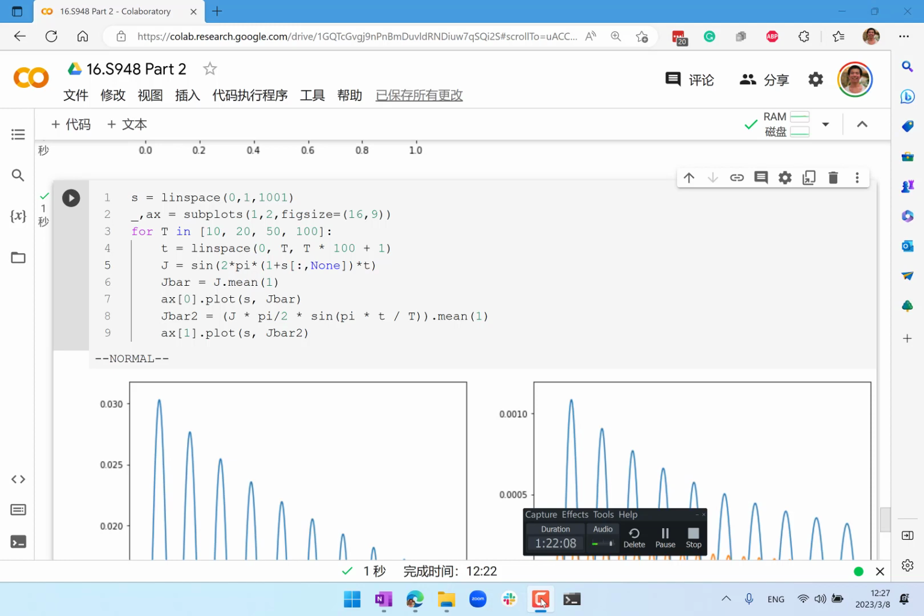You almost always get better results when you're averaging either a periodic signal over non-integer periods, or averaging over a non-periodic signal. So windowing almost always helps in these cases. I have yet to find a case where the square windowing is actually the best, unless you're averaging a periodic signal over integer periods. That's the only case where a square window outperforms all other windowing. Otherwise, there is some type of window that would help compared to the square window.